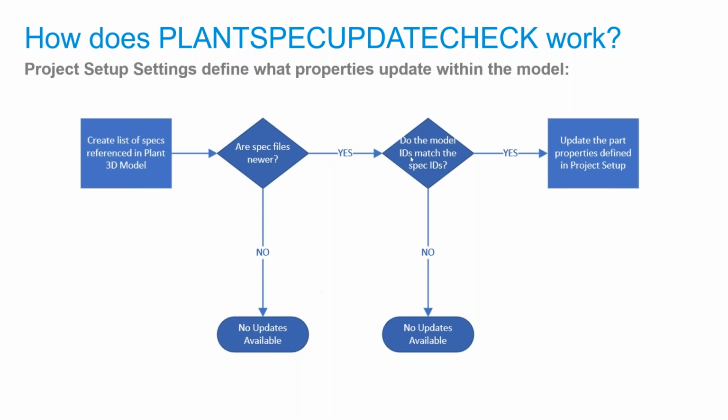No, and this is what happens if you delete families from the spec during the project and replace them with catalog families that you newly insert into the spec. In this case, no updates are available. It will show that, even though there would be updates available. So this is what should not happen, and which you can avoid by not deleting families from the spec.